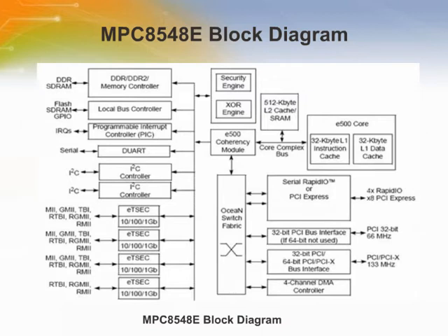The processors are designed to offer clock speed scaling up to 1.333 GHz with headroom for 1.5 GHz. They combine the powerful processor core, enhanced peripherals, and high-speed interconnect technology to balance processor performance with I/O systems throughput. Processors offer a wide range of high-speed connectivity options, including gigabit Ethernet, serial rapid I/O technology, and PCI Express.